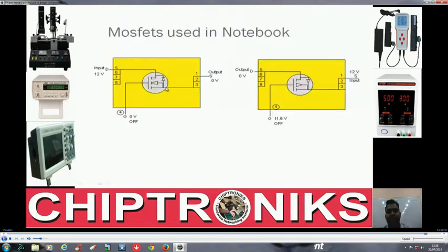As I said, in an N channel MOSFET we have an internal damper diode. Similarly, in a P channel MOSFET we have an internal damper diode. If you put the positive probe at the source and the negative probe at the drain, in the diode range it gives you a value of 0.6 to 0.7, and if it's reversed it gives you OL, then this MOSFET is good. We are basically testing the damper diode. This is one way.